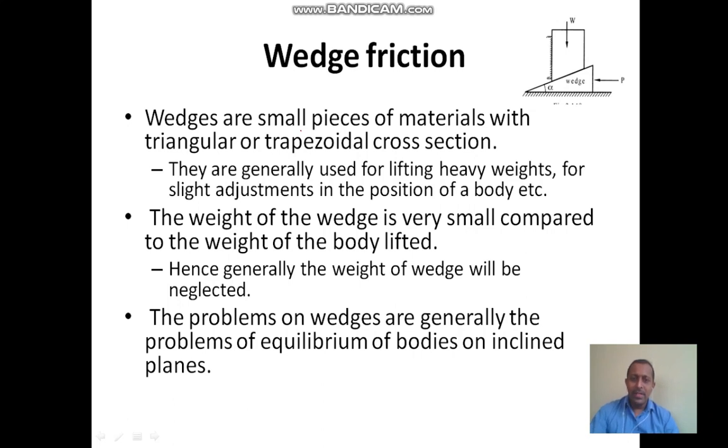The weight of the wedge is very small as compared to the weight of the body to be lifted, so that we can neglect the weight of the wedge for the calculation. The problems on wedges are generally the problems of equilibrium of bodies on inclined planes.